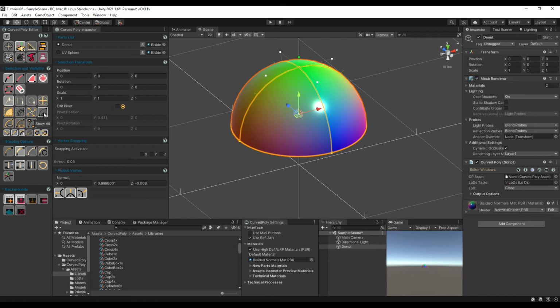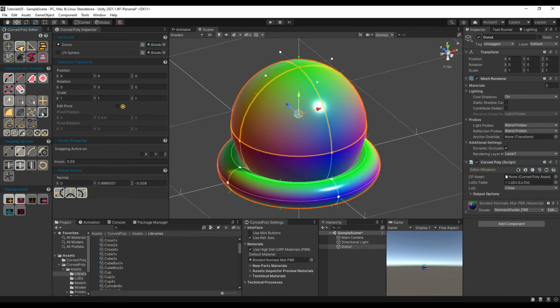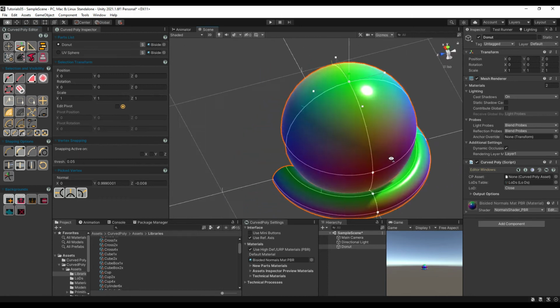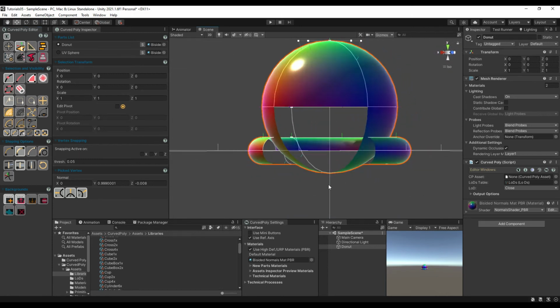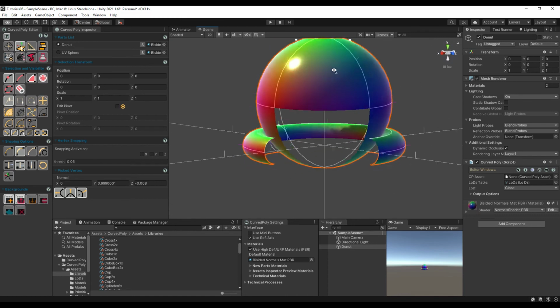There is also an option to hide what can't be seen, where what can't be seen depends on the actual orientation of the camera. So, for instance, if we keep this orientation in the scene window, and we click on Hide Invisible Elements, it looks like nothing has happened, but if we change the orientation of the camera by rotating around the model, we can see that all the elements behind what we were watching have been hidden.